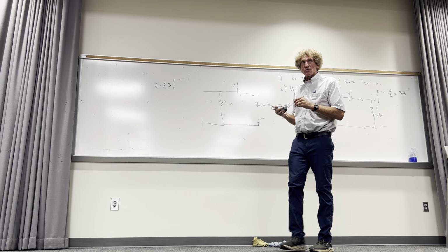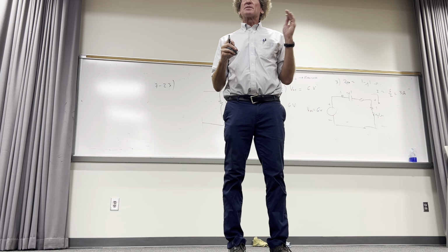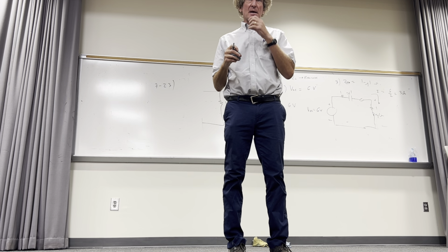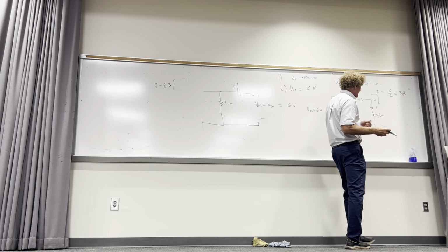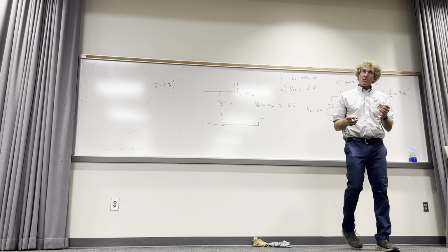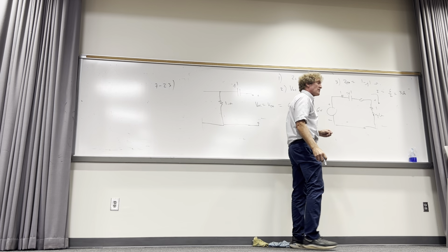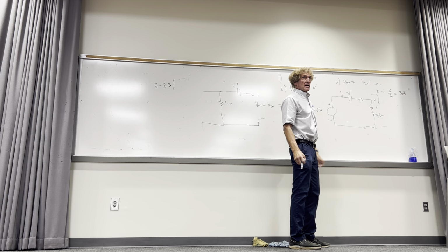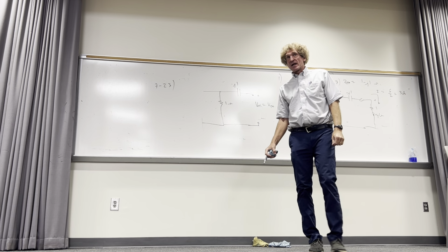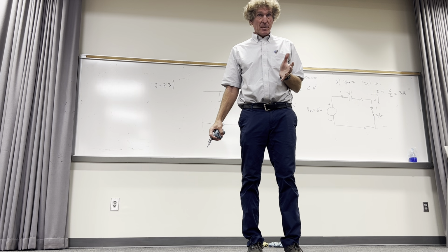How much power is absorbed by that load? Only the resistor would be absorbing power. Do you agree with that? It would be 1/2 times 3 squared, or 9 divided by 2, or 4.5 watts. How many see that? And you will find exactly 4.5 watts will be dissipated here and this one, exactly the same. Go with me? Which means a total of 9 watts was supplied by the source. That's all I'm trying to point out, is the obvious. Everybody with me on this?